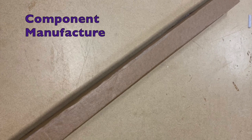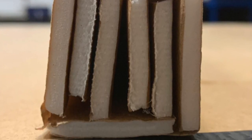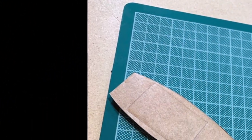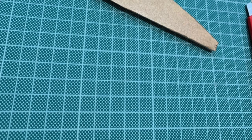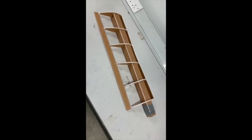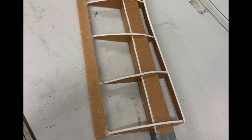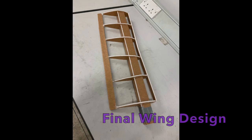Manufacture began by assembling individual components starting with the spar in its rectangular cross-section and increased thickness, then cutting the ribs, leading edge and trailing edge. Precision was used to ensure the spar would fit in the ribs. Once each component was developed, assembly of the final design began, and parts were joined with glue and tape was used for extra support. A simple flat leading edge and trailing edge were used and testing began.